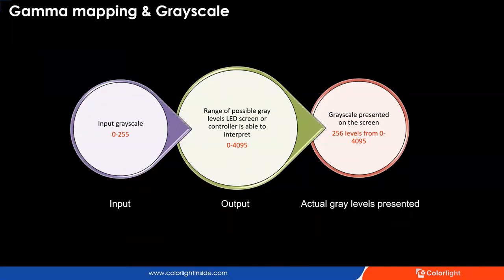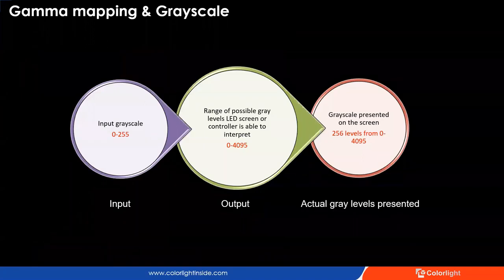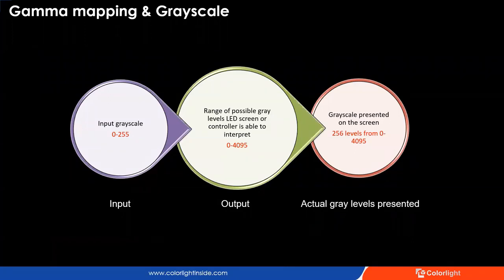Depending on the type of driver IC, there are different gray levels we can set up in LEDVISION software, such as 4096, 16384, 65536. It does not mean an image displayed on the screen will have that number of gray levels. Video input grayscale determines the maximum number of gray levels that can be represented in the image on the screen.